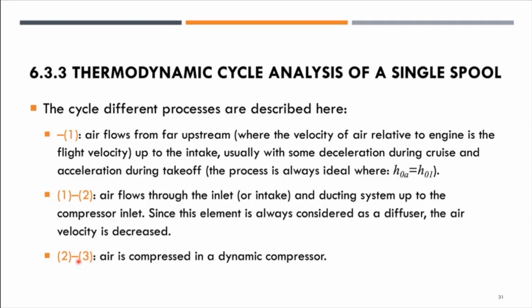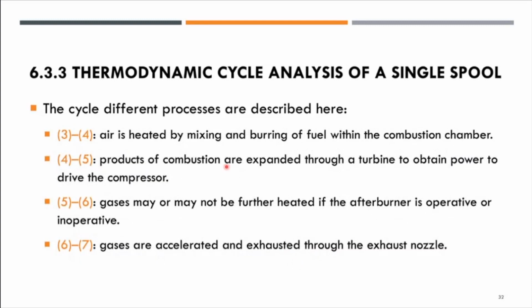And then moving to 2 to 3, where the air is being compressed in the compressor segment, right? And 3 to 4, combustion chamber took place. Air is heated by mixing and burning of fuel. Okay, wrong spelling over there. It is burning of fuel.